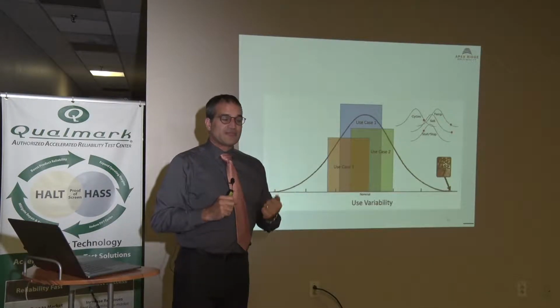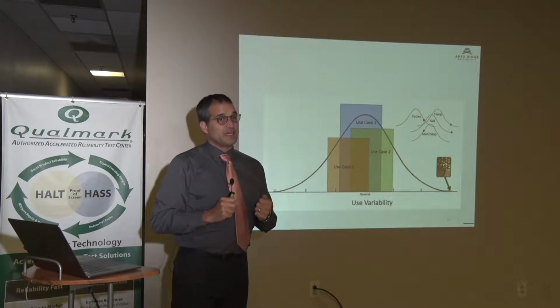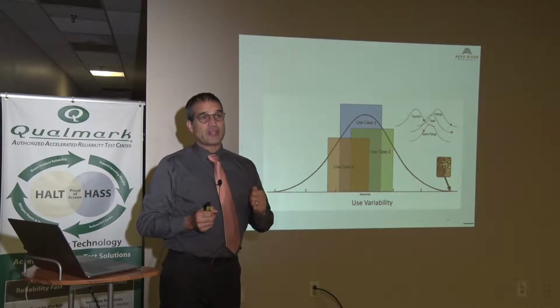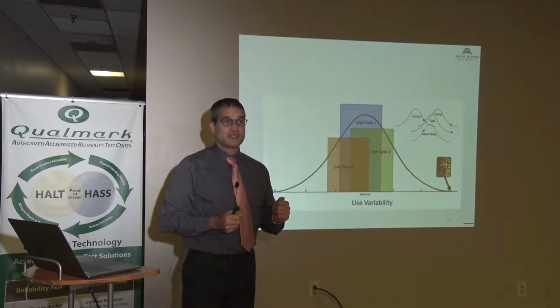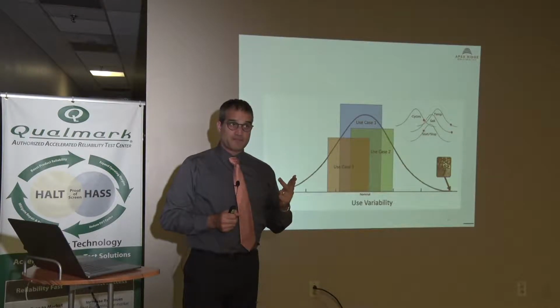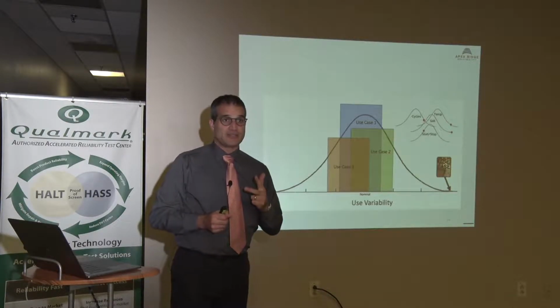And all of those are set at a certain parameter, and you say that's that use case. And you have to remember, any reliability statement we make, you go back to that definition. It's critical that you have a specific use case that you're making that statement on. Remember, the definition for reliability has no value without those three underlying components of how it's used, what environment, and for what period of time. So any reliability test we do that we make a statement on has to be based on a specific use case. So we work hard on getting those defined.